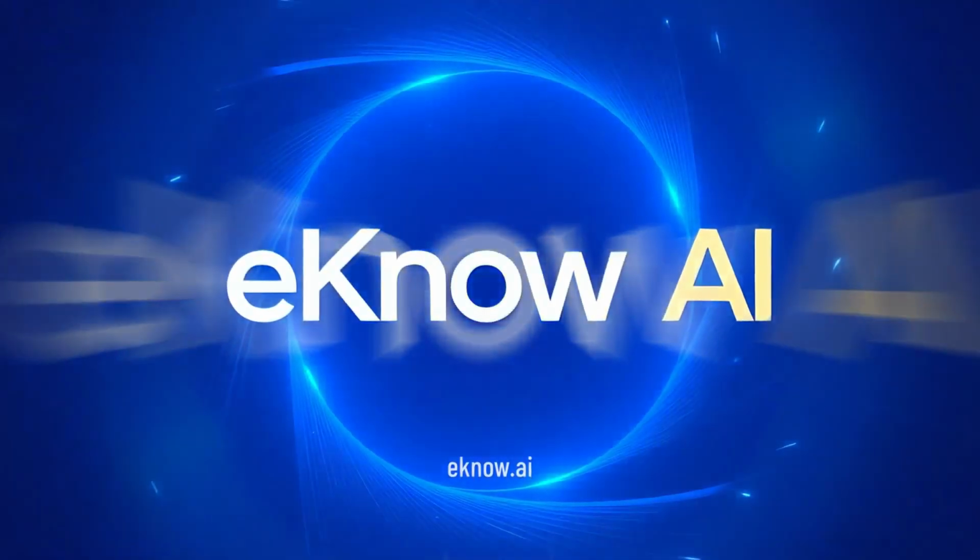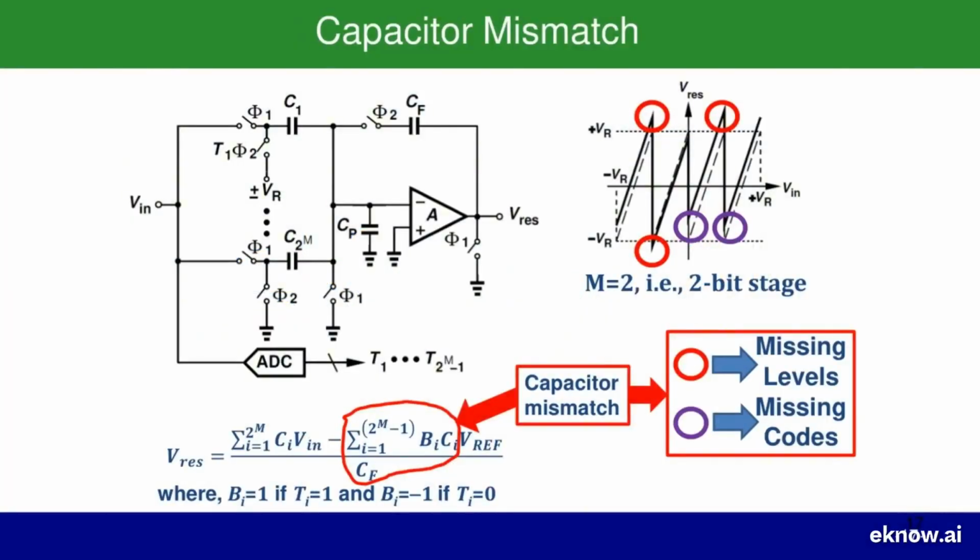Now, let's look at another very important source of error in our pipelined ADCs, capacitor mismatch. In an ideal world, all the capacitors we use in our MDAC circuit would have the exact values we designed them for. For example, all the unit capacitors, labeled C_1 through C_2M, would be perfectly identical. However, in the real world of chip manufacturing, there are always tiny, unavoidable variations. This means C_1 might be slightly different from C_2, and the feedback capacitor C_F might not have the precise intended value. This is what we call capacitor mismatch.